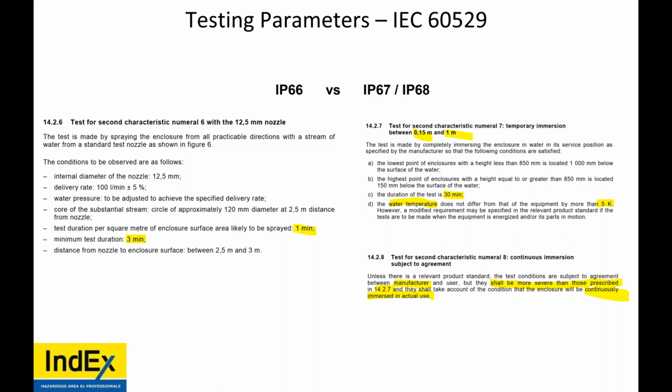Usually when you have a test laboratory test a piece of EX equipment, they'll do the IP testing and the EX testing because it makes more sense for one laboratory to do all tests than to ship the equipment multiple places. So a testing laboratory will invest in IP testing machines, like the ones you saw.